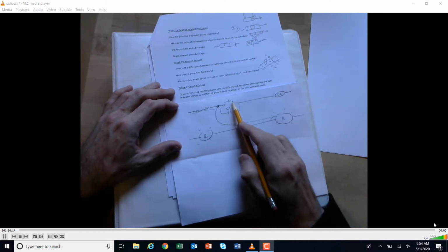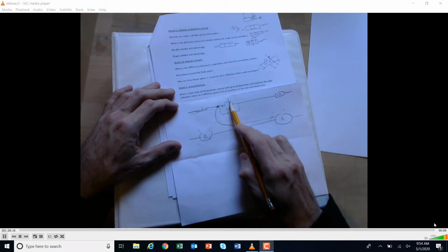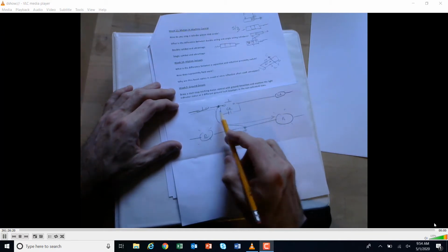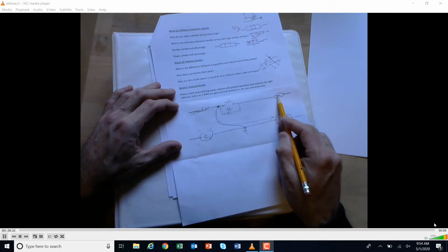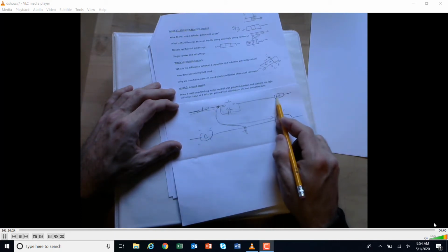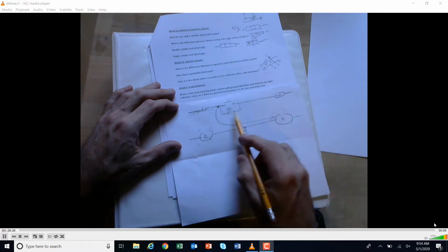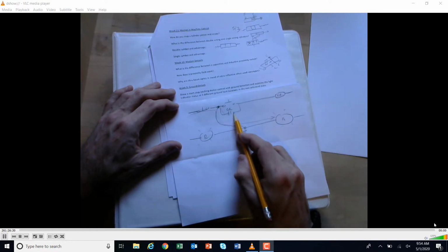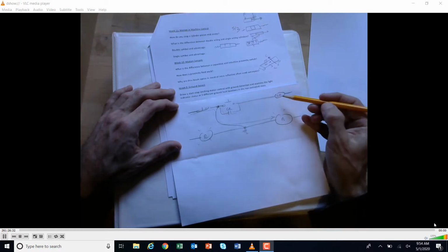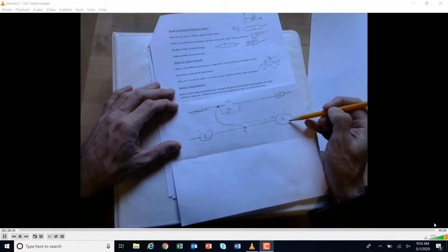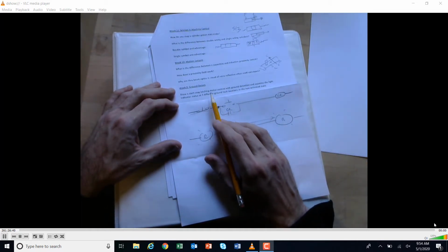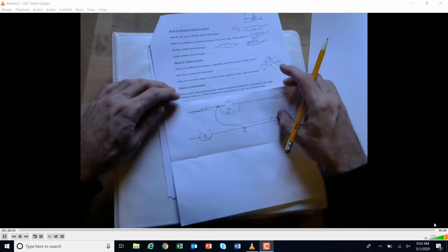And then we talked about, well, what happens if you push the button here? Well, when you push the button, this is going to close, and you let it up. So you would get flow through here, so this control relay would be on, right? But at that point, you just got 2 items in parallel. You've got flow this way, and you've got flow that way. So the control relay would be on, and this ground detect light would still be on. So we went through the analysis of how the ground detect lights worked, and you were given solutions for that.